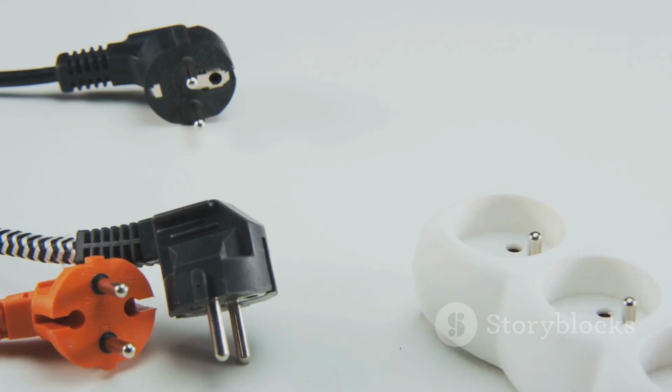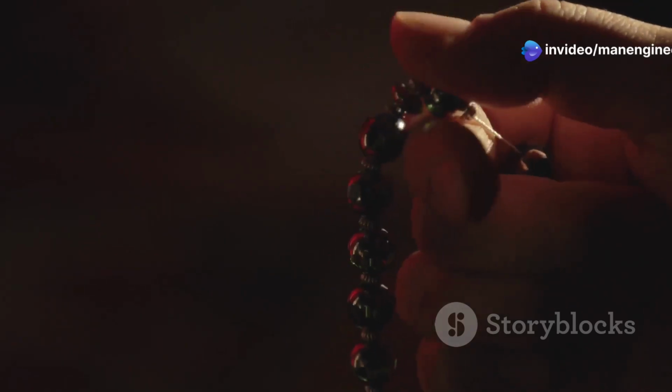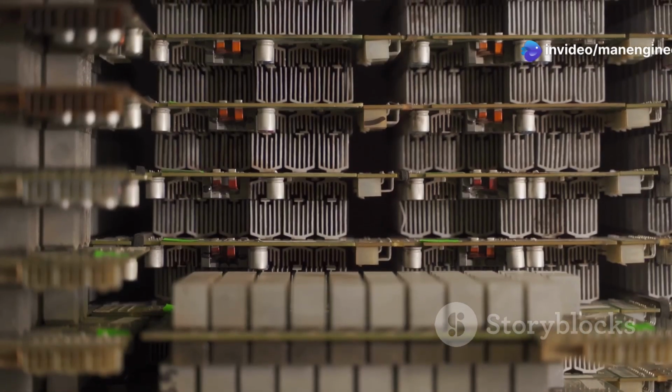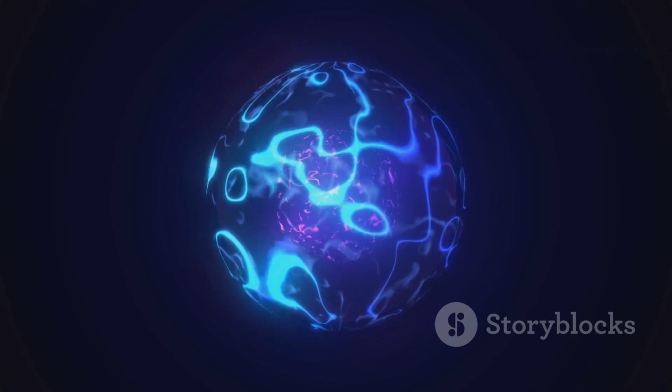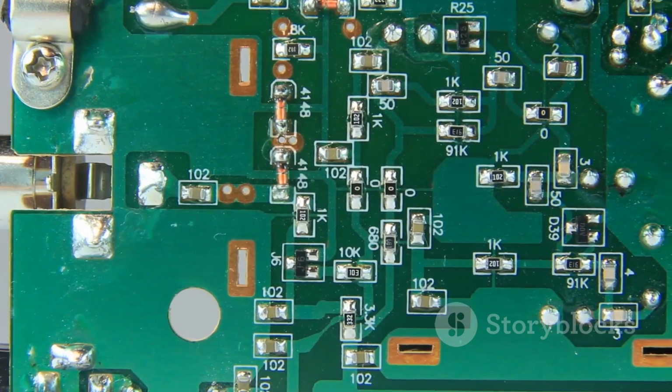Now let's talk about how components like resistors can be connected. One way is in series. Imagine beads threaded onto a single string one after another. That's like resistors in series. They are connected end to end, forming a single path for the current. The very same current must flow through each resistor in the series chain. There's no other way for it to go.